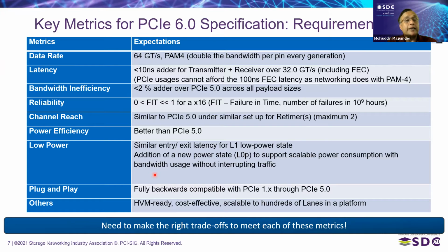So one of the requirements is that even though PAM4 requires forward error correction, which then introduces significant latency, we still cannot allow a hundreds of nanosecond or 100 nanosecond plus latency. Often PAM4 implemented in networking and other industry standard usages is capable. So we will go through how we address that challenge.